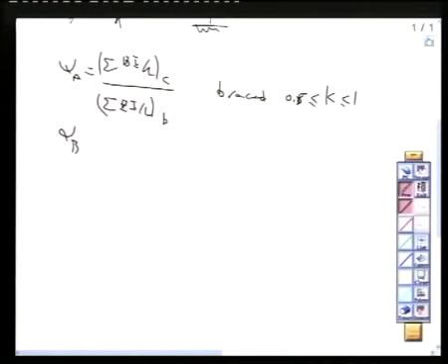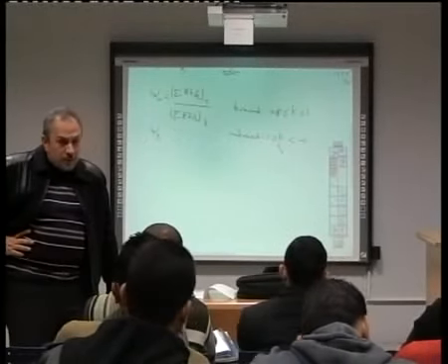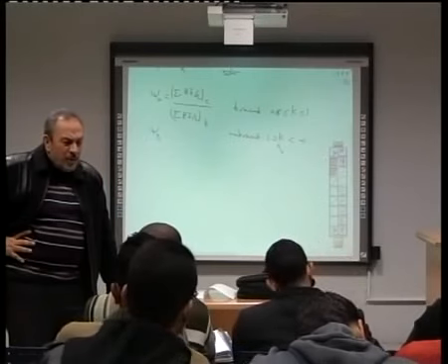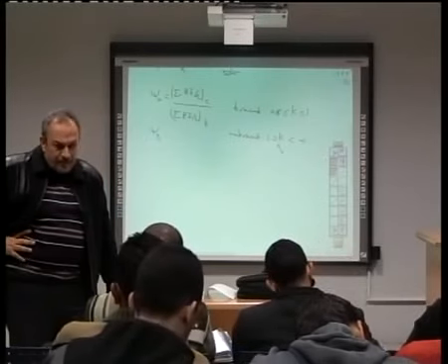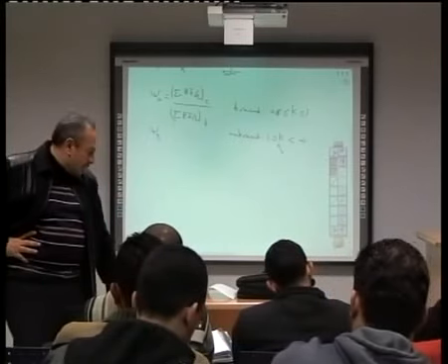However, for unbraced, K is greater or equal to 1 and less than infinity. Here it is very important to calculate K, and we said before that if K is more than 2, 2.3, 2.5, be careful to look again at your structure. I don't recommend using structures with very little stiffness of beams. The more the stiffness of the beam is, the better the structure you will have.